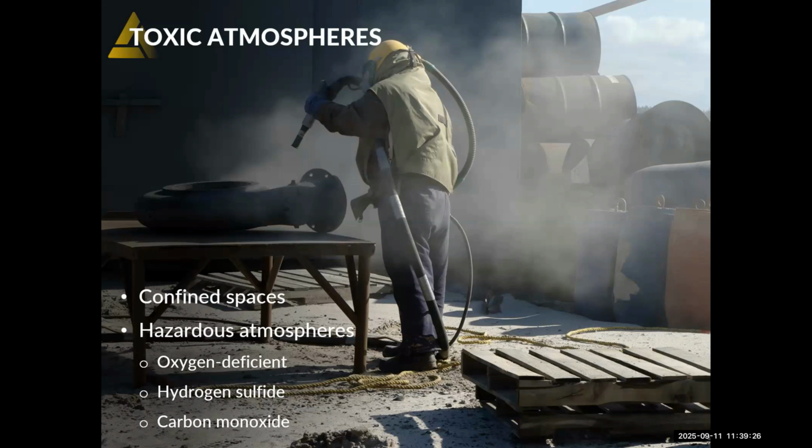If you've got employees that are working in confined spaces, we start talking about toxic and hazardous atmospheres. So first, if you're working in a confined space, hopefully you're following the process, and maybe you've thought about using a gas monitor to check what toxic atmosphere is already in that space before your employees get in there. But then you also have to think a little bit further. If there's nothing in there right now when you begin your work, what kind of a toxic atmosphere is being created just because of the process or the work that's going on in that space?